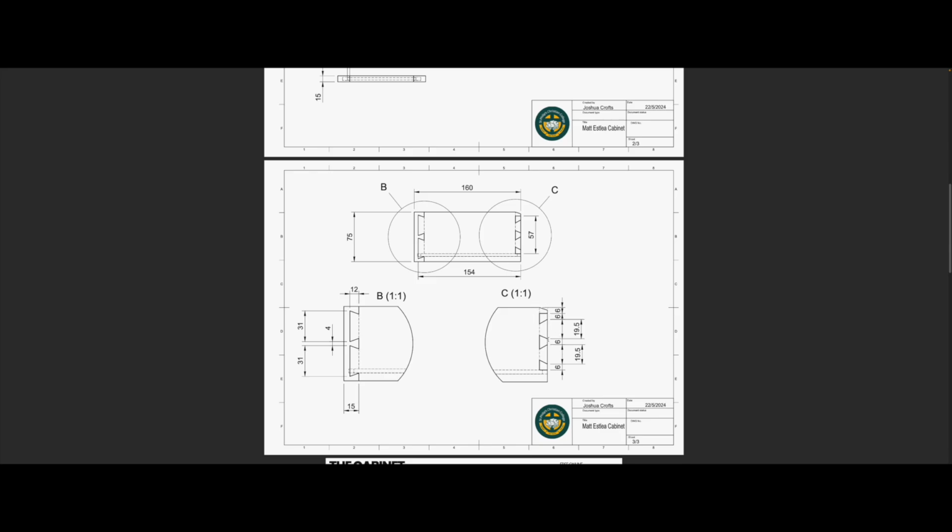So we've got to draw sort of half a dovetail, a full dovetail, and then this funny looking thing again. Why is it like that? Because the back piece of wood in the drawer in this drawing is only 57. So that measurement there is the width of the piece of wood. And then down here, there's a gap in the back. So this is the drawer base in these dotted lines.